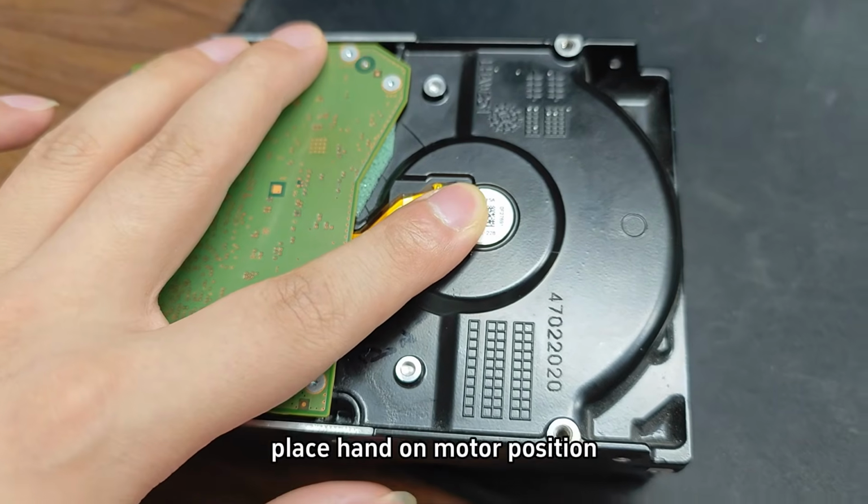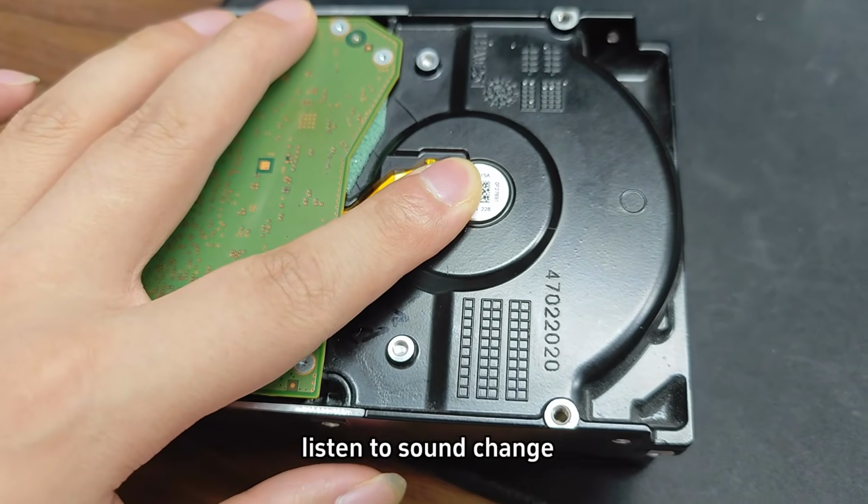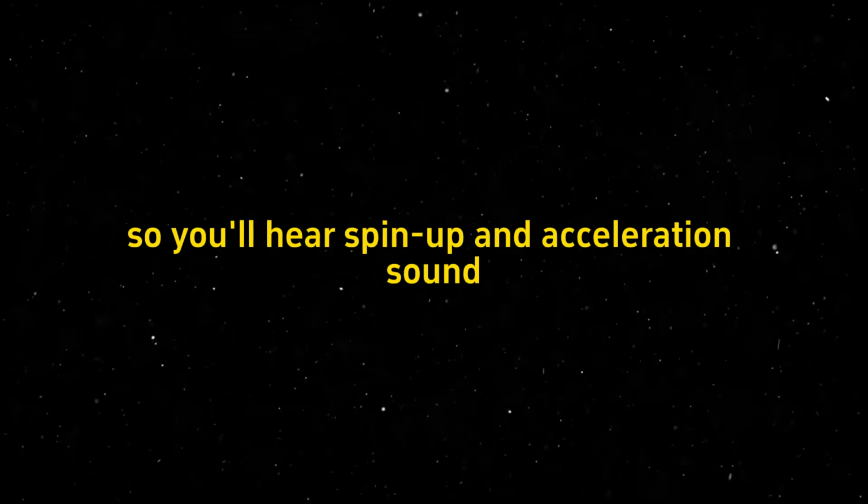Place your hand on the motor position. Feel the power on sequence. Listen to the sound change. In normal startup, the motor spins to target RPM, then heads, seek, and read firmware. So you'll hear spin up, an acceleration sound, stable rotation sound, and head seeking sound. The WD10TB case only has motor sound. Heads do not work, so no head-related commands execute.